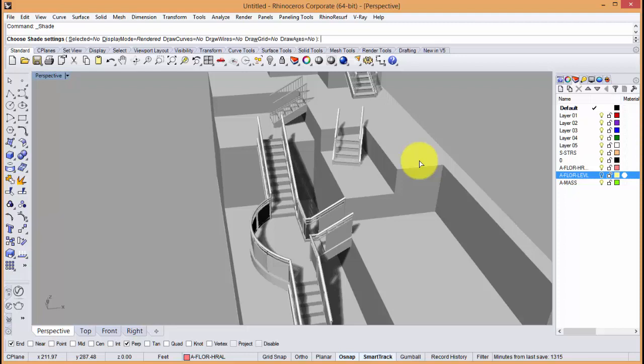However, I wanted to mention it a little bit so you can still use Revit for just the stair. If the level is somehow complex to you, you can create only 2 levels and create a stair and import it to Rhinoceros a couple of times. Just using the stair itself, it doesn't have to talk about anything else. You don't have to use the floor or other components in Revit. Just the stair alone will save you a lot of time.